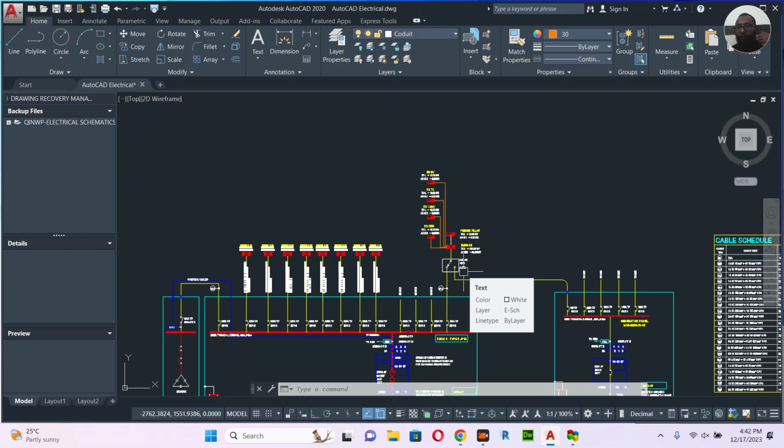So how? There is a panel with relays, too many relays. This relay will operate 240 volts, but to operate itself it needs a very small voltage. One coil is inside. Normally it is the NC NO concept relay. If you check the relay, you will understand. So the relay will control 240 volts. To work itself, it needs very small power like 12 volts, something like that.